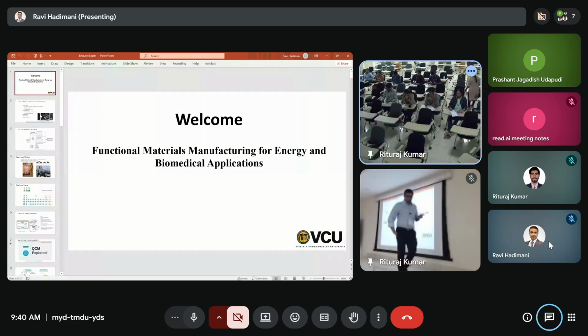You can actually make some materials super hard or super strong or super elastic, whatever it is, you can amplify. That's because when you are at nanometer scale, you can actually control atom by atom, meaning you can really tune the crystal lattice and atomic interactions, so you can amplify any desired property you want. Whereas in bulk materials, that might be slightly difficult.